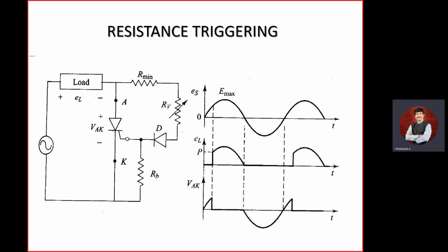Kindly concentrate. This is very important. Why is it not coming down directly? Because of charging and discharging. When it is discharging, it goes through along with the diode. Once it reaches there, your load voltage will become zero, because it is negative and the thyristor is not going to conduct. The diode will not conduct either, since the diode is reverse biased, so it will not send the current. Once it is not sending the current, it becomes an open circuit.